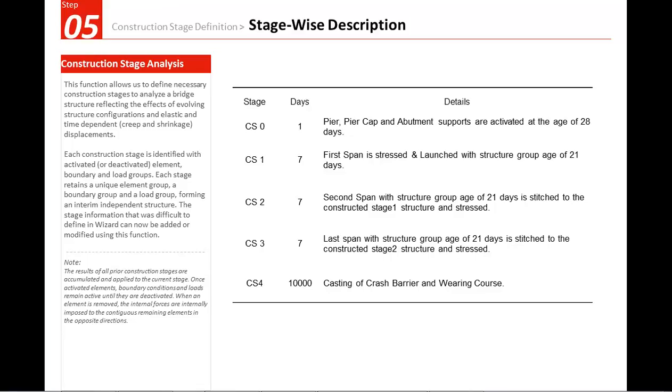So next we'll be doing the definition of construction stage in the software. In the first stage, CS0, the duration will be 1 day and we'll be activating pier and pier cap elements with the age of 28 days.